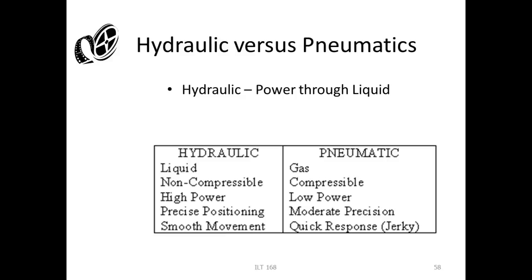So hydraulic systems are a lot more expensive to install. Why is that? Well, a hydraulic system would be a lot more than a pneumatic. But not only that, we have to buy the oil, right? Everything is at such a high pressure, so what does that mean? All our tubing has got to be metal.